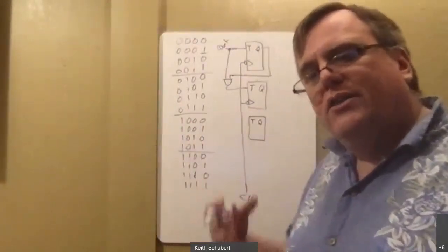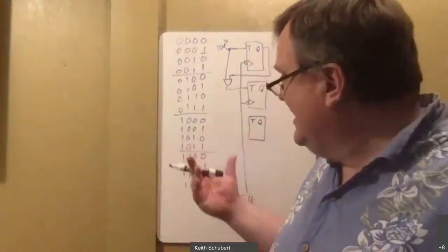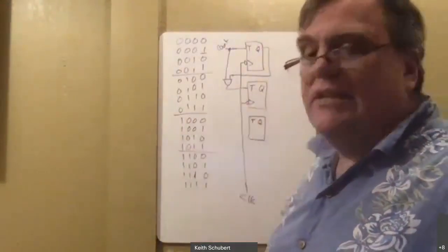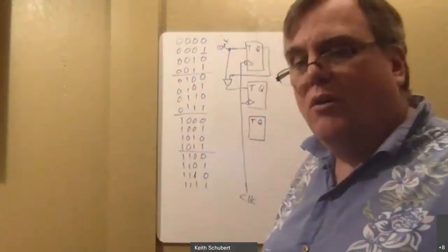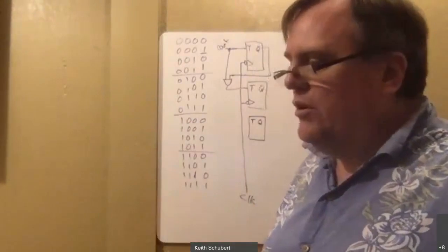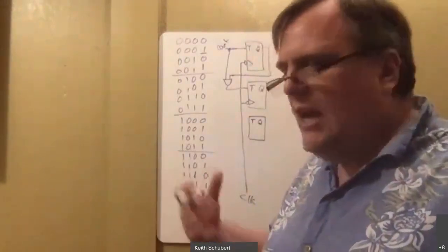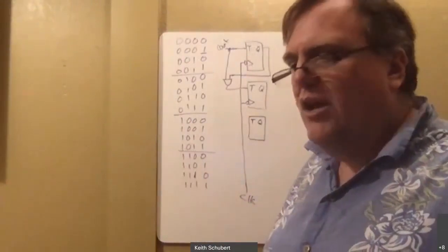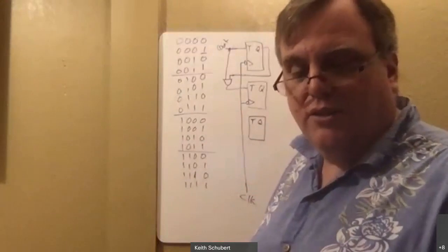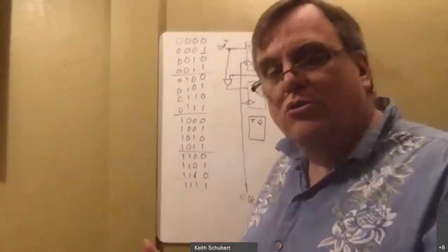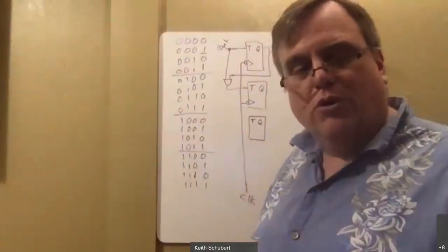So there's another level, and so you could go through all the techniques. Any of the techniques would work. They wouldn't necessarily give you this nice, simple design. K-maps would, right? The K-map absolutely would work. It's big and ugly, but it works. I mean, K-map is always a safe way to go, but as it gets too big, it can become cumbersome. And there are versions of it, Quine-McCluskey, that do it algebraically, and a computer can solve it for you.